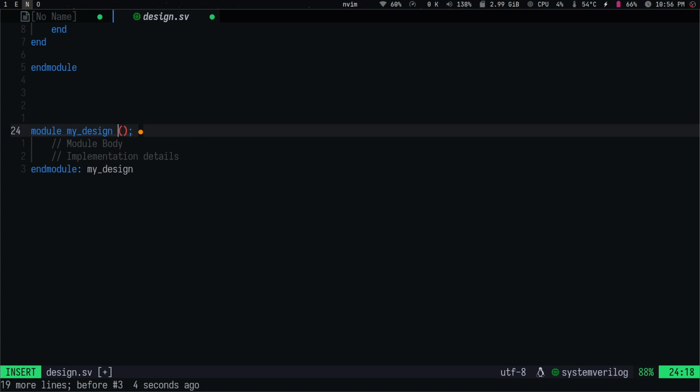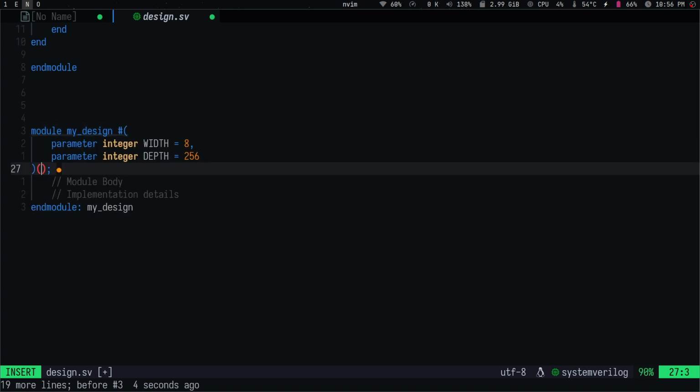So now this is where LuaSnip actually starts showing its true colors. It's really powerful. So whenever it shows me this yellow dot, it's telling me that this is an option node. It means that I can turn something on or turn it off. So as you can see, I can press something, I can then turn it on, and then here it tells me that with SystemVerilog modules, if you have, let's say, parameters to the module itself, these are like generics in VHDL. So these are the sort of things that you sometimes might have or might not have. So that's why these are options here.